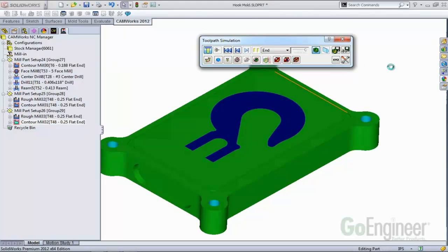But what about those mounting holes? Remember I chose a reamer for those holes. Most likely what's happening at this point is that, I have to admit, I created this model. I didn't create those holes. The size of those holes doesn't correspond to a standard reamer size. So if the programmer saw this, they'd probably come back to the designer and say, hey, do you really want these holes this size?